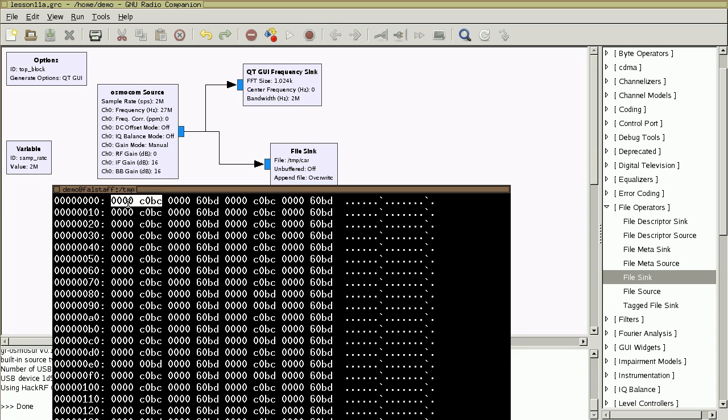So what we have here is one floating point number for I, and then another floating point number for Q, and then the next floating point number for I, and floating point number for Q. And there will be a limited number of values used here, even though it's 32 bits, well really 64 bits for a single quadrature sample.